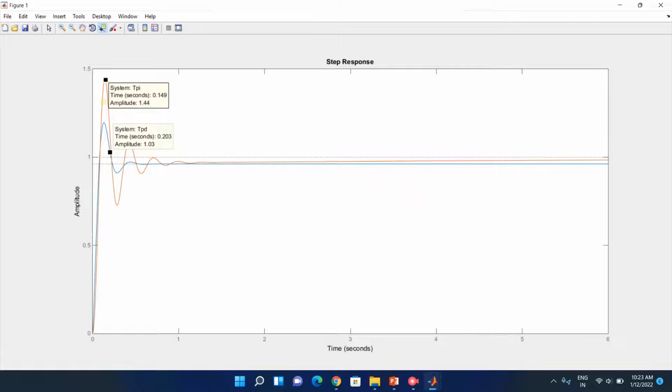That is why, since the derivative controller is not there, for the PI controller with proportional gain 500, as you used for the PD controller, there is a problem. For PD also we used Kp as 500, but the derivative controller has the capability of reducing the overshoot by implementing damping. So you can see it has damped and the steady state has been reached very early.